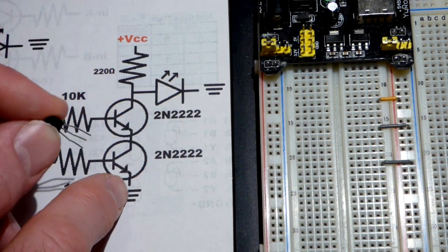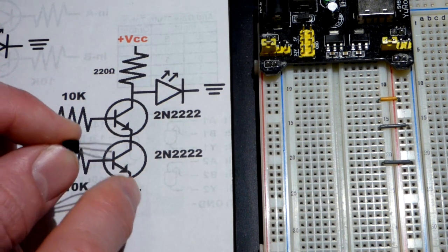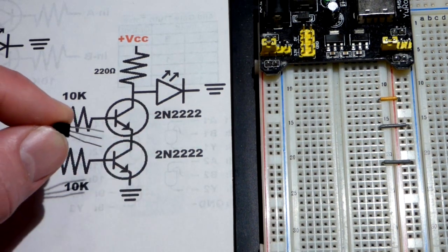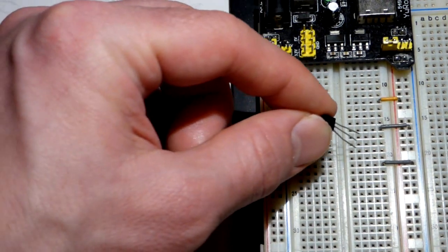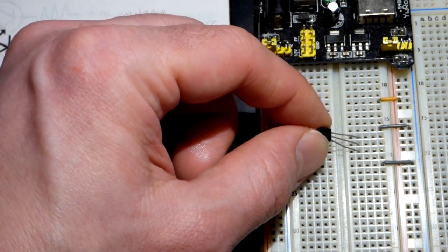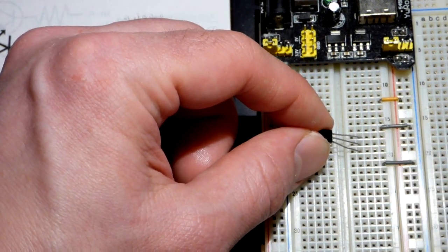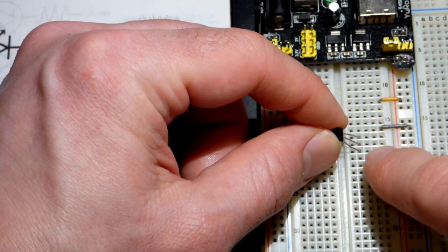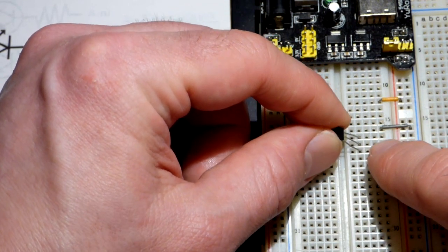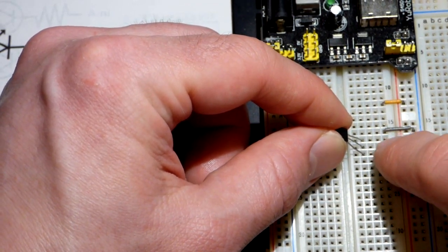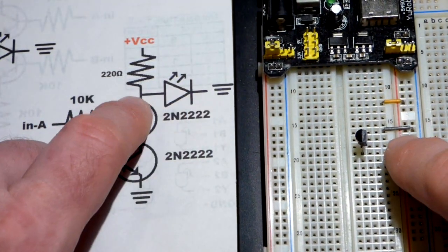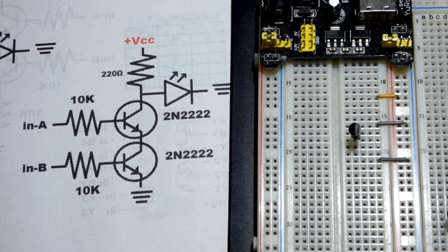And then emitter down here we're going to put at the bottom, so I'll turn it to the right for when it fits in the board. Base, middle pin, collector up there, top pin. And of course I'm putting the transistors in first. They have 3 pins that aren't very flexible, so usually I put them in, and then the other components I adapt to fit with them. So I'm going to put it one space below the gray jumper there, because again we're going to have the LED going to ground. LEDs, you can stretch out their pins, but I try not to.